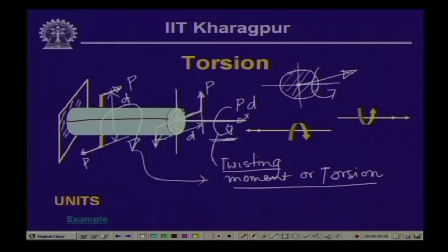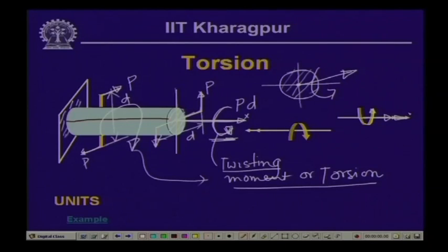In the first case, we had the moment acting about the x axis in an anti-clockwise direction. If you look at this figure, where this is the axis, the twisting moment is acting in an anti-clockwise form. Here it behaves like a right hand screw. If the moment is acting in this form, the direction of the axis is towards the thumb. This is what we call a positive twisting moment, where the vectorial direction is in the x direction. So, the moment is acting on the bar such that the thumb is directed towards the positive x axis, and this we call a positive twisting moment. Whereas, when the moment is acting in a clockwise form, the thumb goes opposite to the positive x direction, which we call a negative twisting moment, and the corresponding rotation a negative rotation.